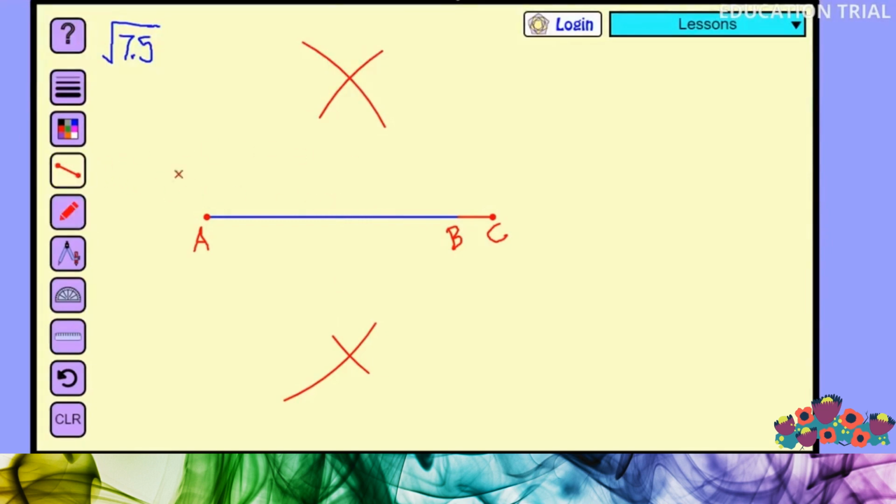For this, I am drawing a straight line from these two intersecting points and connecting with the other arc intersected point, so that I will get the midpoint of this line segment AC. That midpoint I mark as O.